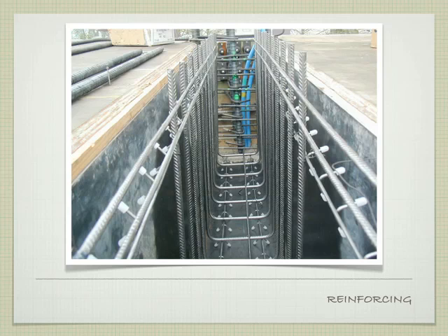They're also using chairs on either side to make sure that that stays its correct distance. And so if you think about trying to do this, this would be a lot easier if you put these continuous chairs. You tie it up on the top surface, then you lower it down into place, and you know it's in the right position.